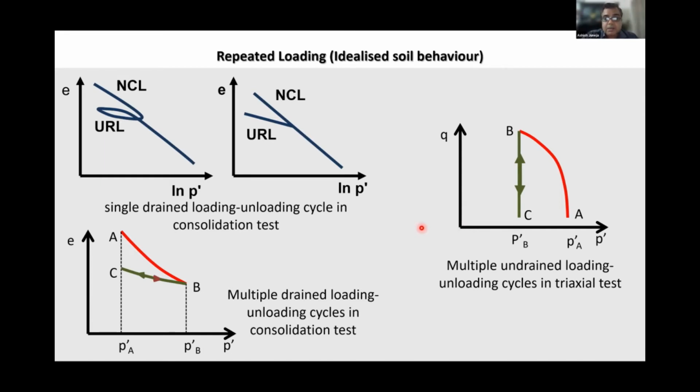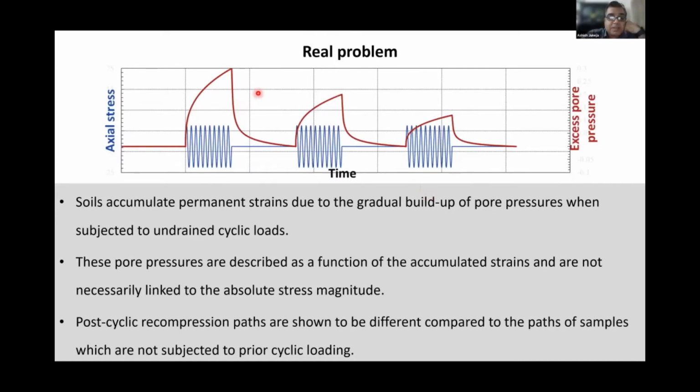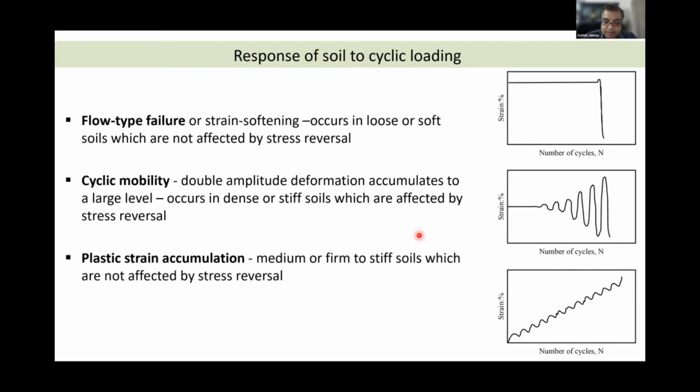Okay. However, if I have multiple load cycles going on over a certain period of time, what you see is the pore pressure development in the first cycle, and then in the second cycle and third cycle, it's not the same each time. You do see a different response, which is more like a real life scenario. So the bottom line is you do need something like a slightly more sophisticated soil model to understand this phenomenon which occurs.